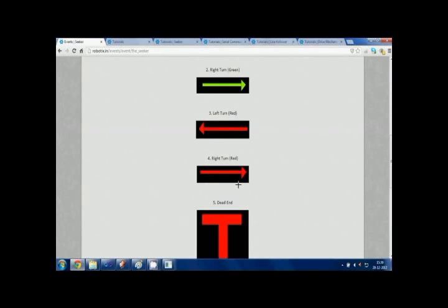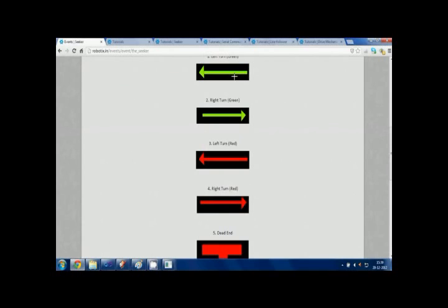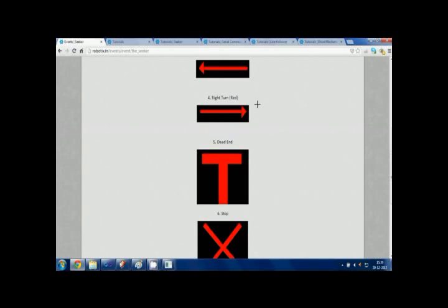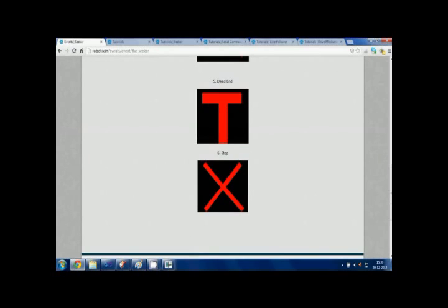And again, keeping in mind the color, you can also find out exactly what the category of signs is. Will it be a sign allowing you to do a particular thing or a sign disallowing a particular thing? And once you have done all of this, you will send the appropriate instructions to your robot, make it start turning, and keep turning, if it's an arrow of course, until you find yourself at the center of the next corridor, again by using Hough Transform, and then you can move on.